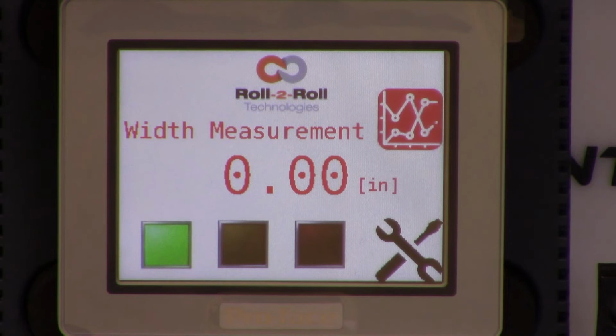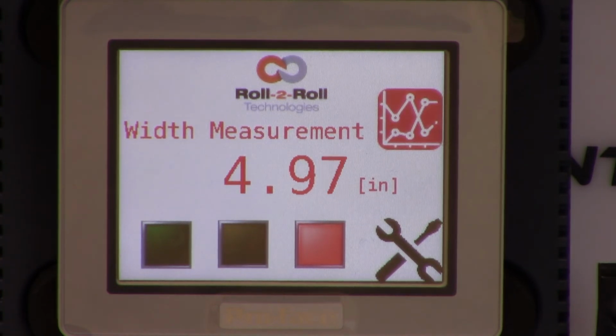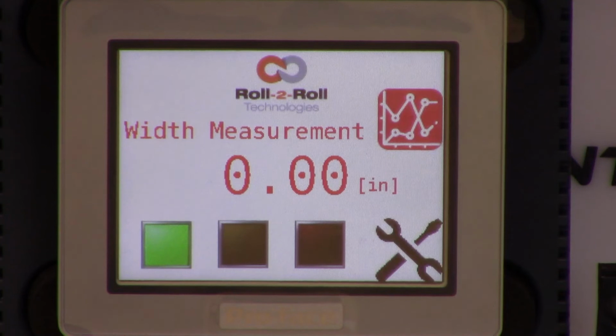As you can see on the home screen, there are three lights available. These are the three digital outputs. In order for us to run a stack light, we take the data from the SCU5 and then use the recipe or the settings on the PLC, so that you can set up upper limits and lower limits for the alarms and warnings. That way you can connect it to a stack light, and the stack light would go on based on that.